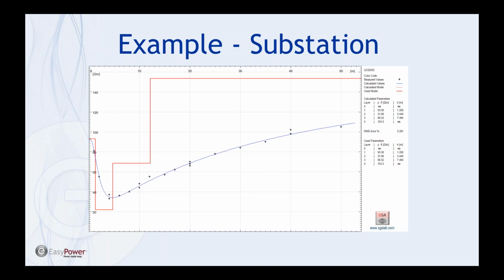And the next thing that you would do in a grounding analysis program is you would determine your soil model that you apply to the preliminary grid that you've imported. You know, what's your grid sitting in? What we're showing here is a multi-layer soil model, and it's based on soil resistivity measurements. The black crosses represent the measured values of soil resistance for each spacing, and the blue is a curve fit on top of those. The soil model, finally, in red, is one that has been calculated based on the measured values. The program iterates until it finds the model with the least error.